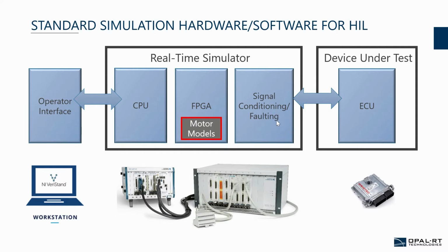Here I have a DUT connected to an SLSC chassis. SLSC stands for Switch Load and Signal Conditioning, and is a hardware platform with many types of channel options. After signals are conditioned, they are passed along to the FPGA instrumentation. In this diagram, the electric machine models are compiled into an FPGA bit stream and then loaded into the FPGA at execution time. Since the FPGA is reprogrammable, we can support multiple types of machines simply by downloading different bit streams depending on the application.